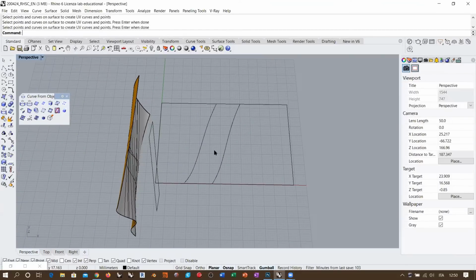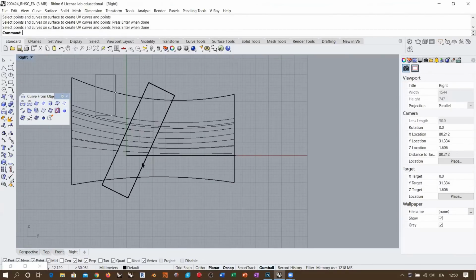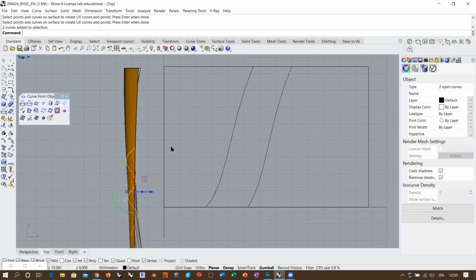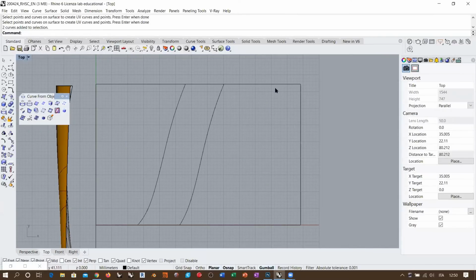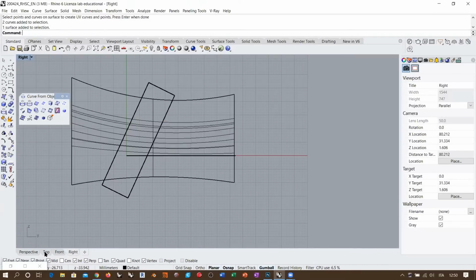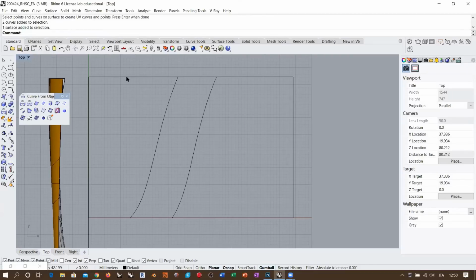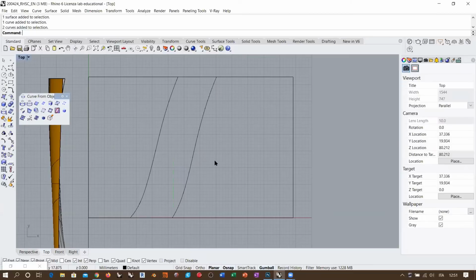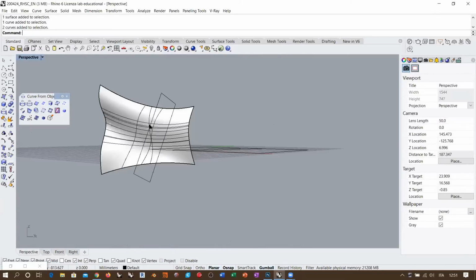Now you see that even if from the right viewport those two lines are basically straight and parallel between them because they come from a projection, when you work with the parametric representation inside the parametric domain it becomes rectangular and the lines become wavy. So geometrically, we have a wavy surface and we have parallel lines. But topologically or parametrically, we have a rectangular surface representation and wavy lines. Okay, so our text must become wavy in order to be applied properly inside this area.